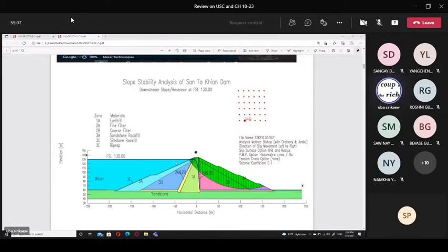Engineers control the water head, the pressure of water that forces it to spill out or drain, through what we call the filter zone. To make it heavy, we use rock fill at the upper part, like a shell, like a cover, to protect the clay material or the impermeable zone, covered by heavy material.